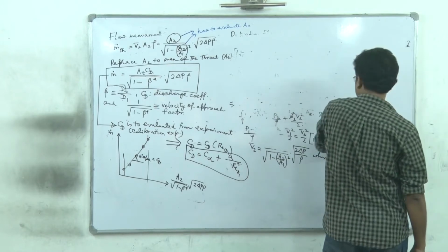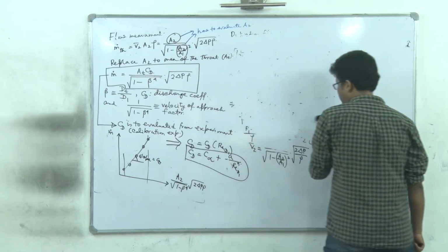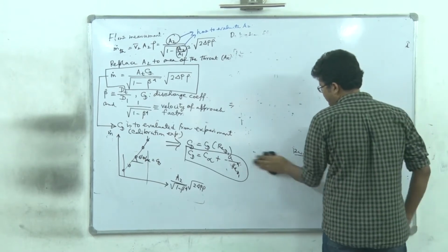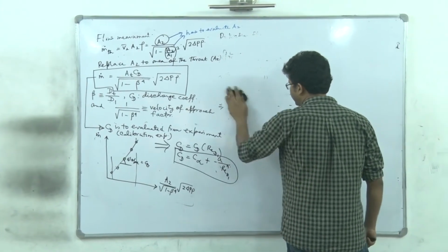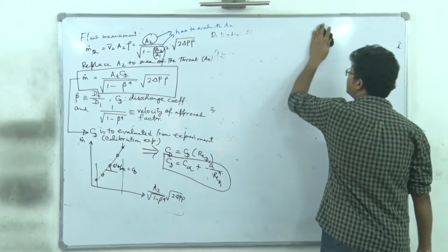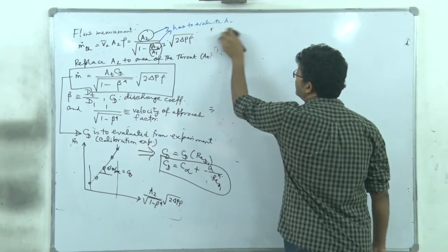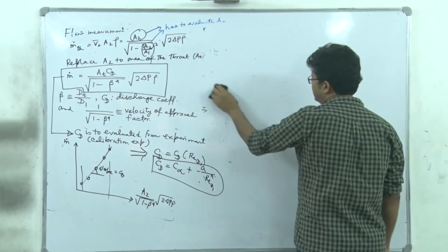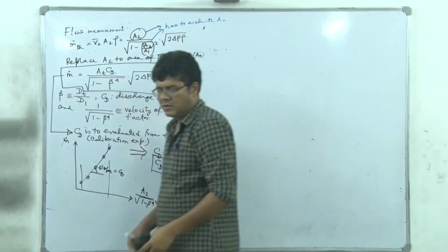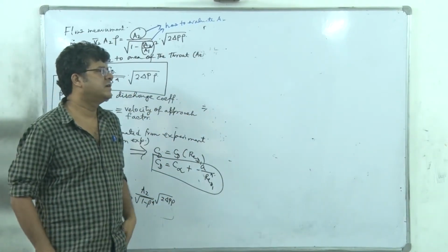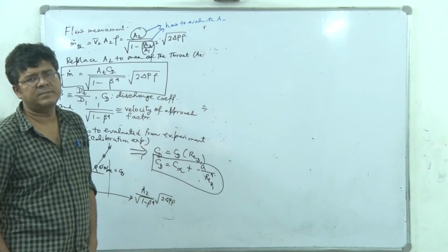Orifice meter is just a disc with a central orifice, right? In common design it will be a central orifice, which is inserted in the pipe segment between two flanges, right? So it's a small, compact, handy structure and it's quite flexible.